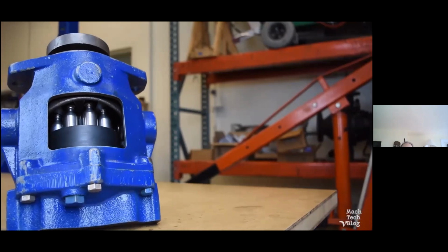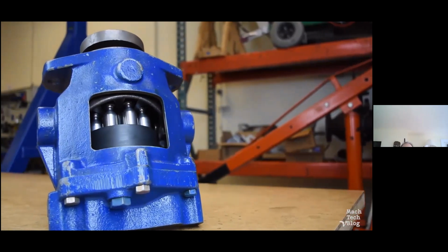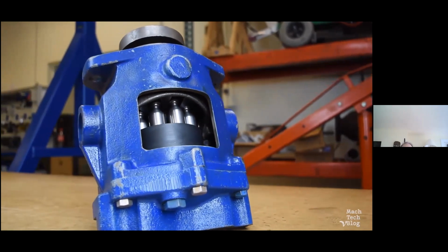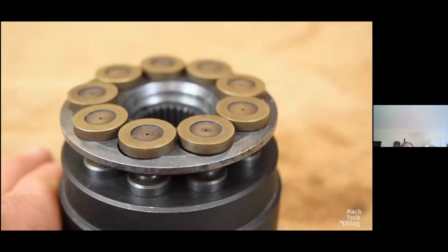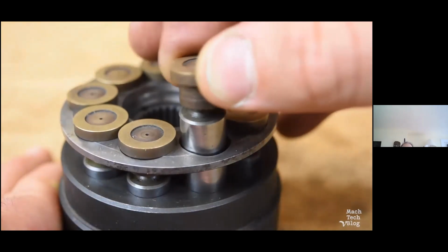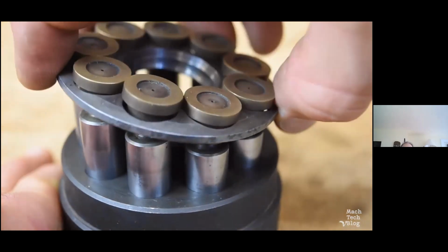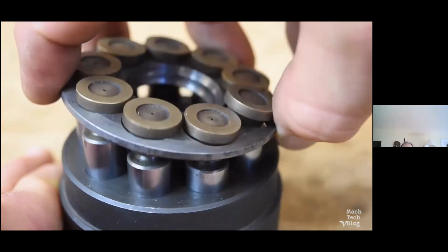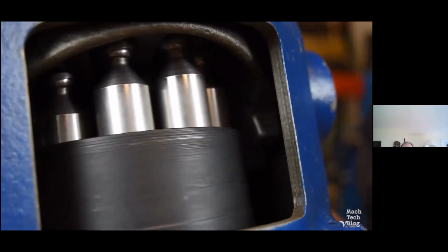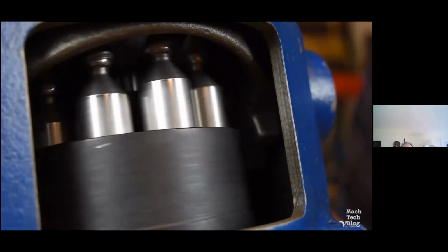Here's an example of a common piston pump called an axial piston pump. This pump is a tad more complex than our little demonstration, but the pumping action is generated in exactly the same way. The axial piston pump has multiple pistons equally spaced on the end of a rotating angled plate. As the plate rotates, the pistons are driven into and out of their respective cylinders. You can clearly see the motion here. Like most reciprocating pumps, piston pumps are relatively efficient, and they're capable of generating very high pressures.